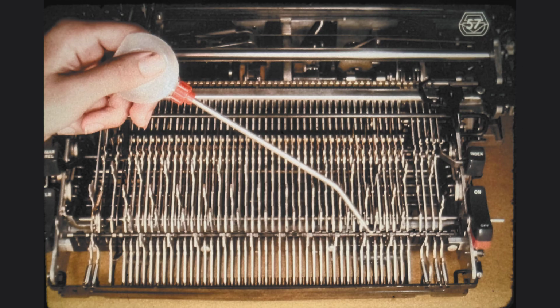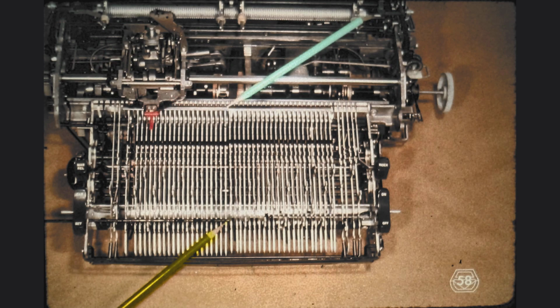Once this has been done, it becomes rather simple to extract the rod through one of the openings in the keyboard side frame. In order to show you a few things on the keyboard, we have removed all the keytops, as you can see, and we have left half of the keylever upstop rod in position. Green pointer. We shall proceed by pivoting the keylever's top to the rear, and we have made sure that we are in a position to lift all the keylevers which use the right keylever pawl restoring spring. Notice the point indicated by the yellow pencil, which marks the separation point between the 2 keylever pawl restoring springs.